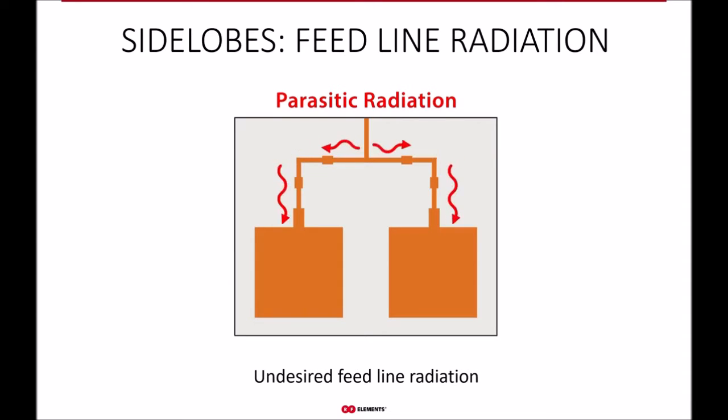Second major cause of the side lobes of patch arrays is parasitic radiation. And here we look at two components. First is the radiation of the feeding lines. So to bring the feeding signal to each patch in the array, a network of feeding lines is used, which is basically symmetrical division of the line until we get as many outputs as is needed, as is the number of patches. In this example, you can see 2. So at the top, there is that vertical line, and that's branching to 2. So we can feed our 2 patches.